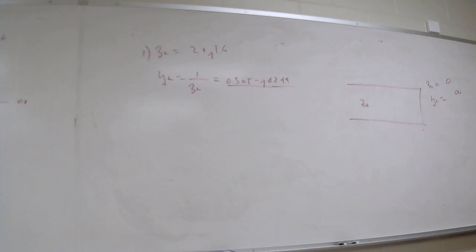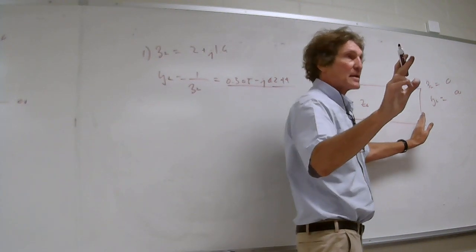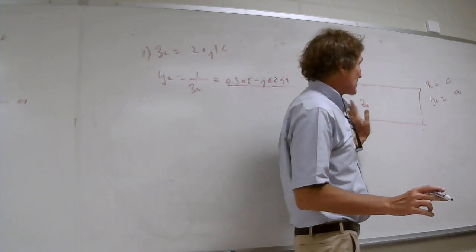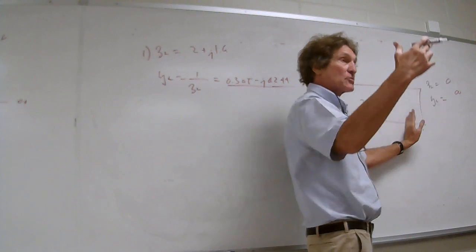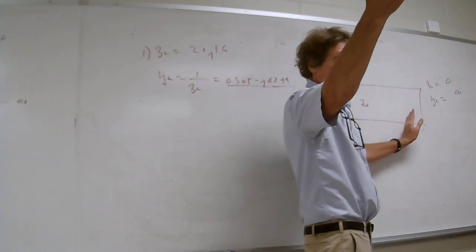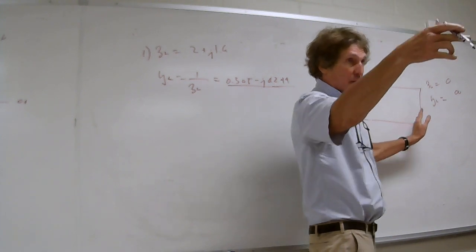And so a negative would be closer to the positive because we go through the negative side. We first want the minimum. This is the minimum distance, right? We don't care about the distance from the load, just the stub length. The stub length starts negative just as you move an inch, so we have to match it to a positive j value for the load's intersecting point. 1 plus j something. You all with me?